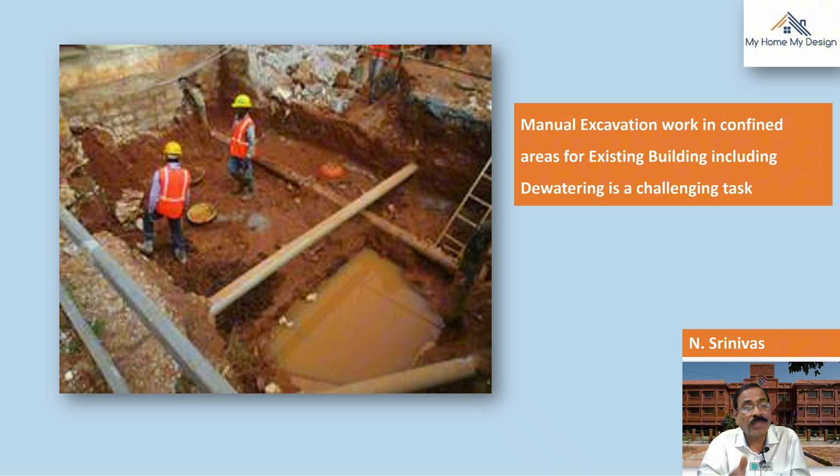Either you need to go for a temporary wall structure to arrest the seepage of water, and then with the help of pumps you take out the water accumulated in the foundation trenches and do the compaction properly. Again PCC has to be done, then steel reinforcement for the footings, and then footing concrete, like that, until the temporary wall you have built has sustained the already seeping areas, so that overflow water is not allowed into the freshly laid concrete. So some measures have to be taken and the seepage has to be arrested.